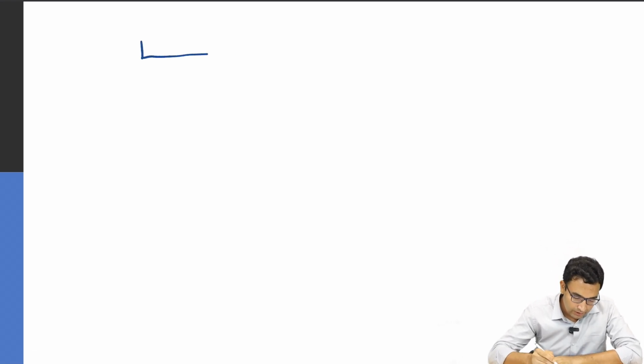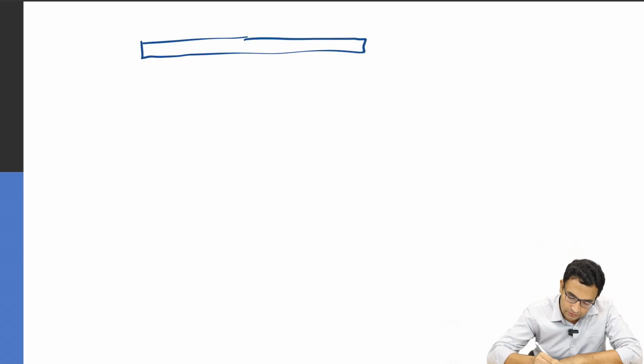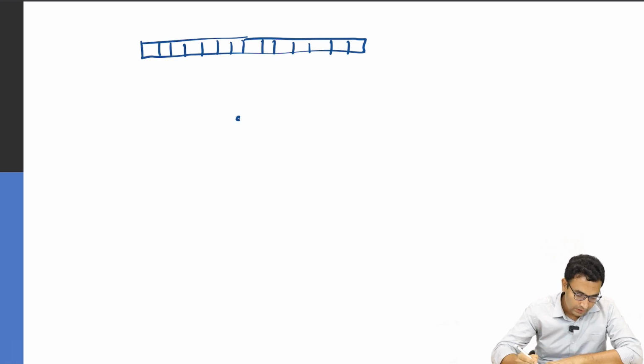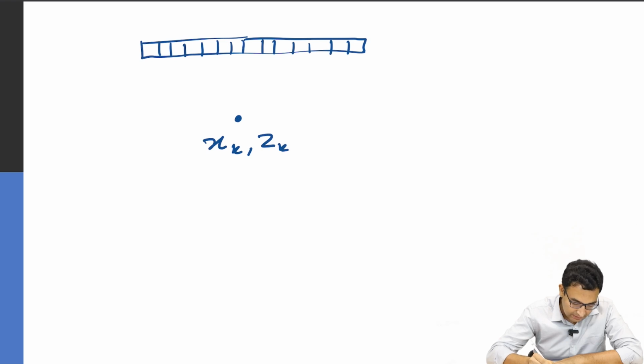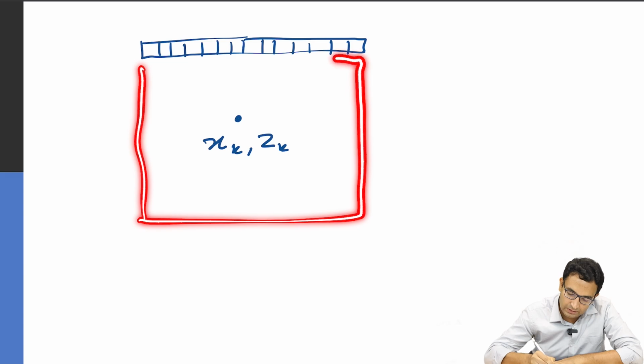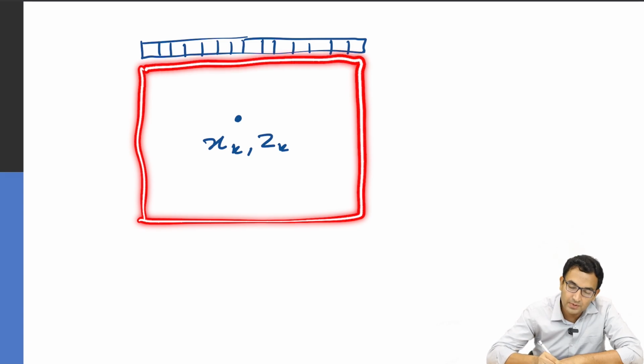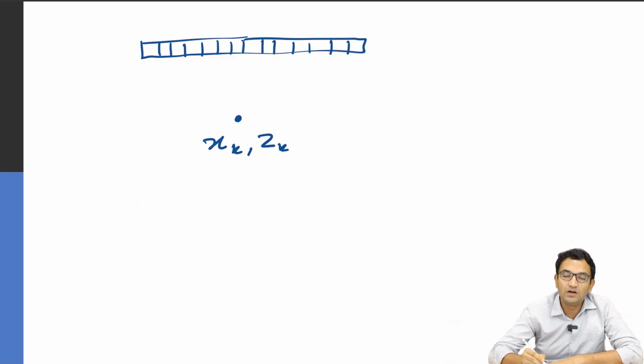So now consider a transducer array, looks like this. And any point which is given by xk, zk. Okay. So we can assume a grid, and the grid's depth will be determined by the depth till which we are imaging, the width will be determined by the array aperture, etc. And based on that, in that grid we choose a particular location that may denote a particular pixel.